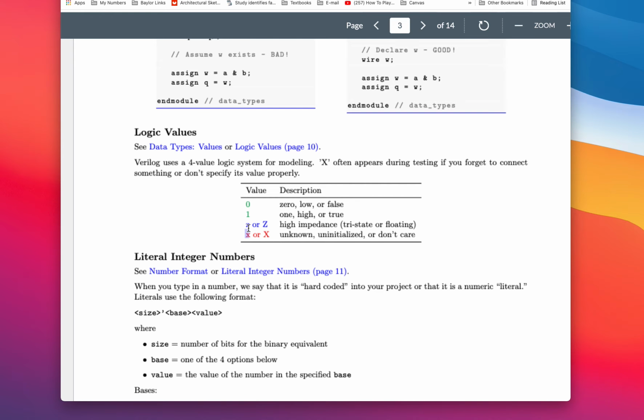All right, and so sometimes we will want to have logic elements that either work, 0 or 1, taking on different logic conditions, or we might want to have that part of the circuit effectively disconnected. So if we can drive that into a high impedance state, by the way we configure the silicon, that's good too. And so Verilog has a way of modeling that.